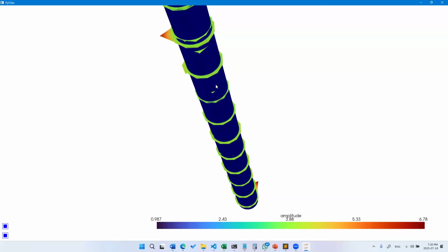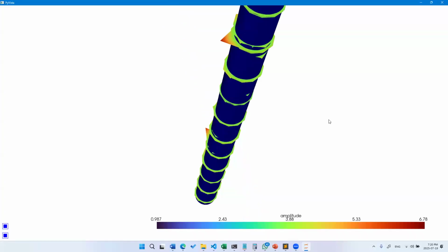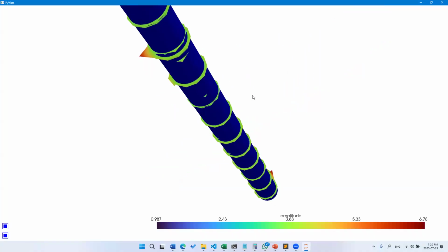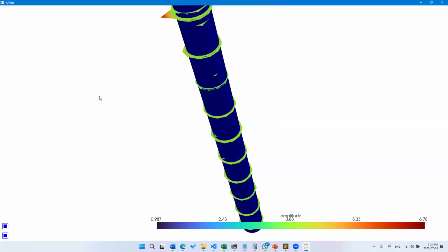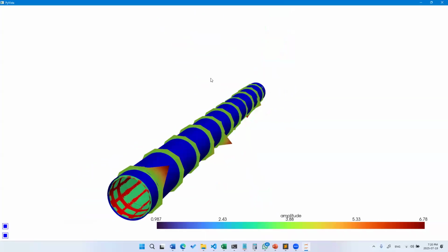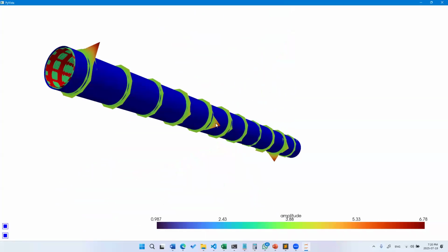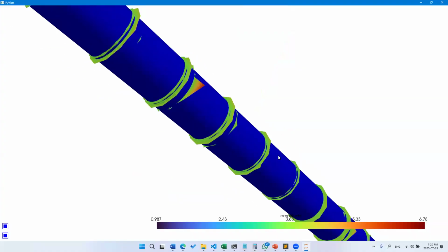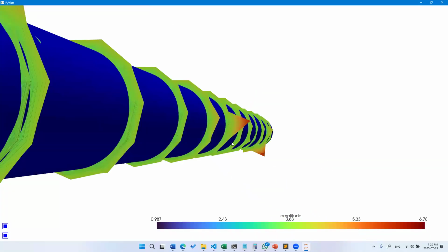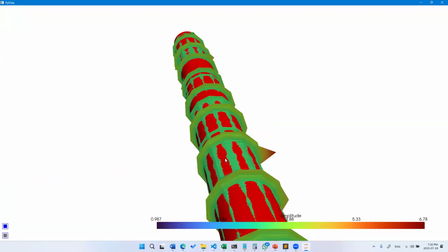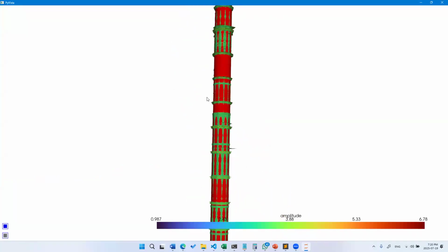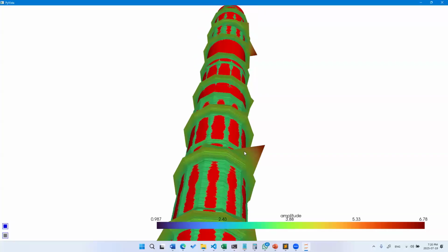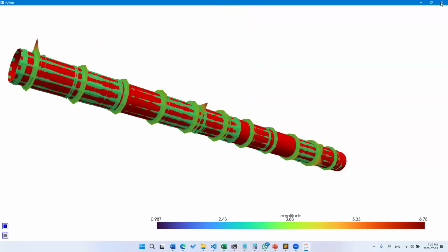All of these rings that you see are the tool joints, which is understood because we did not take them into account. But anything other than these tool joints, for example these spikes, means there might be some puncture, or let's say there might be some problem with our tool integrity. So we can turn these off, and we can also see some corrosion patches and some deposition patches as well. So yeah, this is how you can use these tools for analysis.